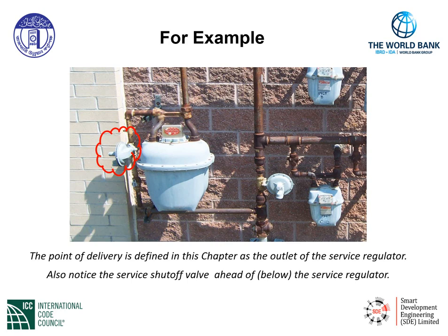What's clearly marked here is you can see towards the middle of the picture, the gas piping system comes up from an underground supply and it rises up into a T. The left portion of the piping system from the branch of the T goes up and services the service regulator and enters the meter and supplies gas to the consumer side.